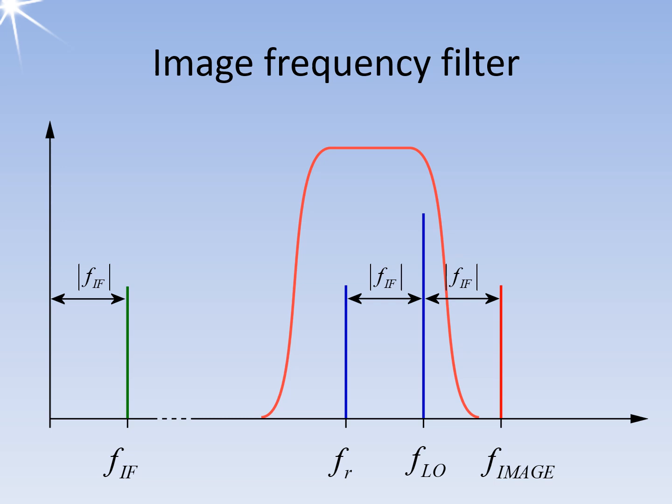An image frequency filter is a bandpass filter that narrows the tuning range of the received frequency. This filter is used before the first mixing stage to block additional noise and jamming signals. The bandwidth of the image frequency filter should be slightly smaller than or equal to twice the intermediate frequency.